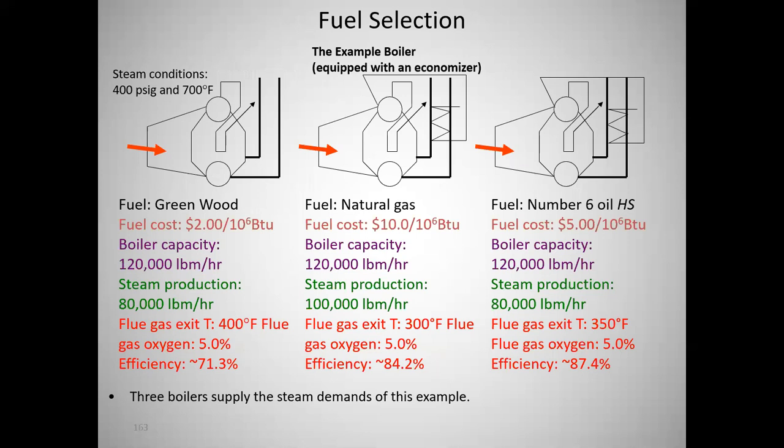So, shoot, I could sure switch 20,000. You know, sometimes it's not a great idea to run a boiler all the way up to 100%. I would not recommend that. If I was doing this for a customer, I would probably recommend 20 or 25,000, because you're not pushing it all the way to the max.